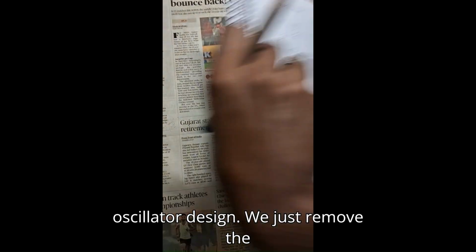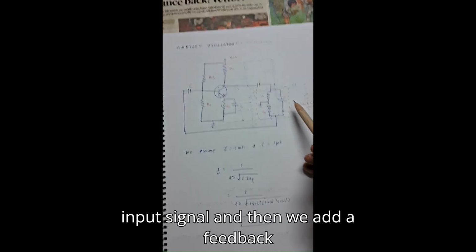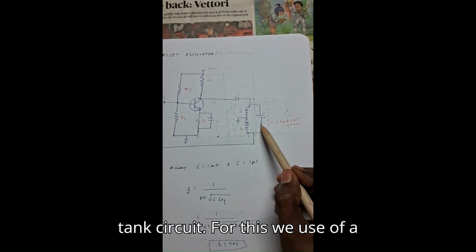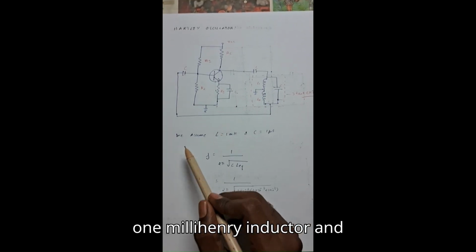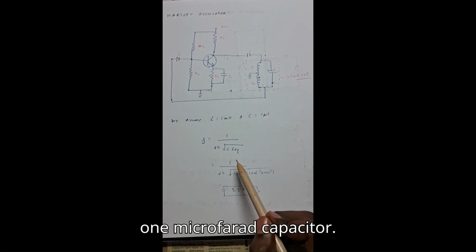And now we come to the oscillator design. We just remove the input signal, and then we add a feedback tank circuit. For this, we use a 1 millihenry inductor and a 1 microfarad capacitor.